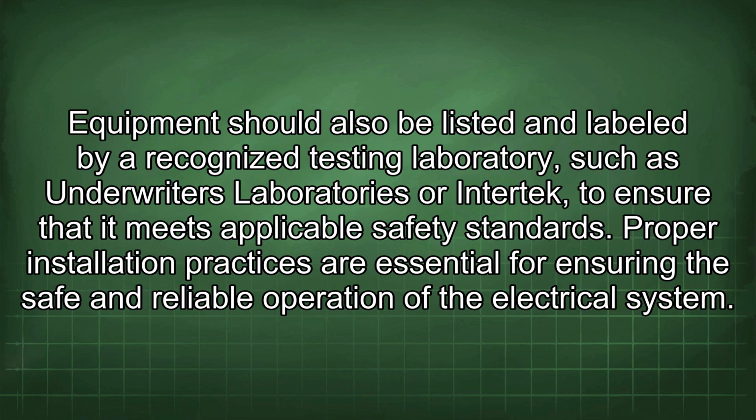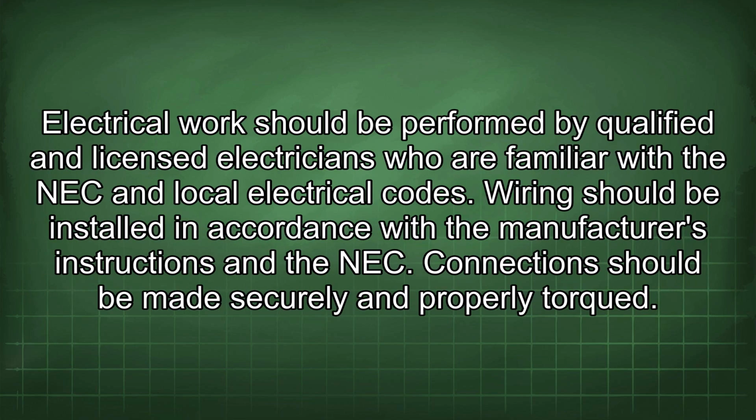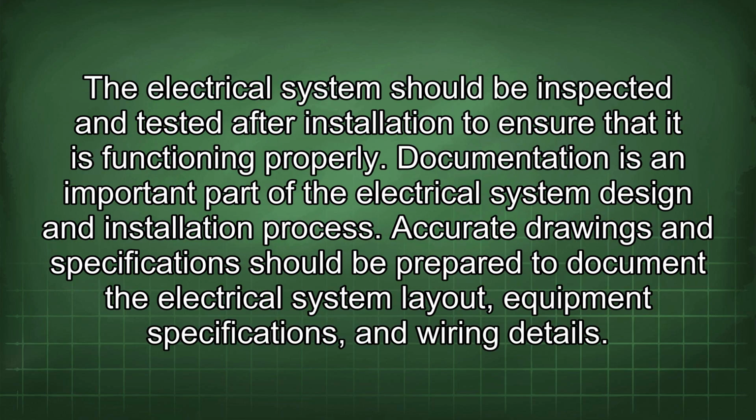Proper installation practices are essential for ensuring the safe and reliable operation of the electrical system. Electrical work should be performed by qualified and licensed electricians who are familiar with the NEC and local electrical codes. Wiring should be installed in accordance with the manufacturer's instructions and the NEC. Connections should be made securely and properly torqued. The electrical system should be inspected and tested after installation to ensure that it is functioning properly.